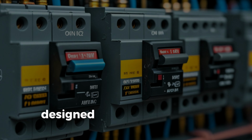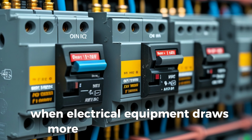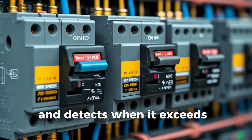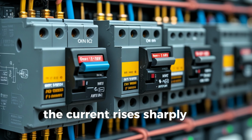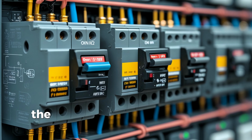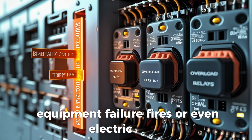1. Circuit breakers. Circuit breakers are safety devices designed to protect electrical systems from damage caused by short circuits and overloads. In the event of an overload, when electrical equipment draws more current than it is rated, the circuit breaker monitors the flow of current and detects when it exceeds a preset safe limit. Similarly, during a short circuit, where electricity takes an unintended low-resistance path, the current rises sharply and dangerously within a fraction of a second. When either of these fault conditions occurs, the circuit breaker automatically interrupts the electrical flow, disconnecting the power supply to prevent overheating, equipment failure, fires, or even electric shock.